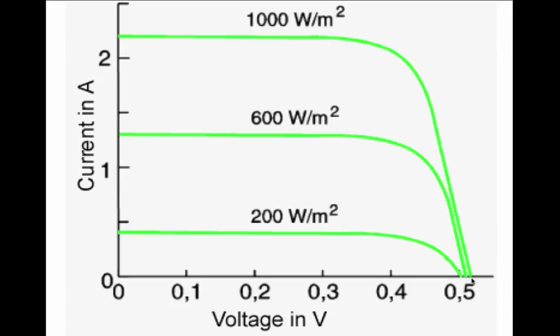Just like if you measure the voltage on a battery when it's at rest, it'll be a certain voltage. But with a solar cell, when you start putting a load on it and working up this curve and actually starting to draw current from it, so let's say we're up here at 1 amp of current, the voltage will have drooped a bit, and then it'll continue to droop till we get to what's called the knee of the curve, this very sharp section where the curve makes a very sharp bend.